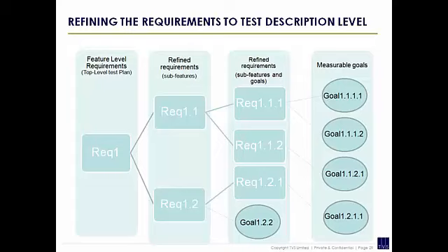So sometimes in here, you can map it to a directed test, because as soon as you're giving the same seed, you're getting the same test. So you can actually map to what we would call directed tests, and directed means the same seed does the same thing every time. Okay? And so all we're doing here is different goals. So what you need to be able to do is map your requirements to different verification goals